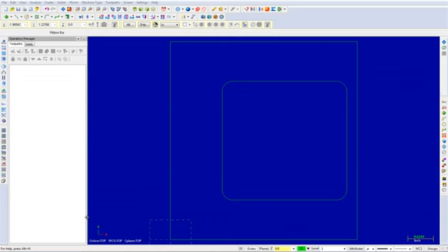Make sure that the construction mode is 2D. From the status bar, click on 3D as shown. This will toggle the construction mode to 2D. From here, click the Z in the status bar. Input a value of -0.25 and press enter. When we create our geometry, we will be creating it at a depth of -0.25 and in the top construction